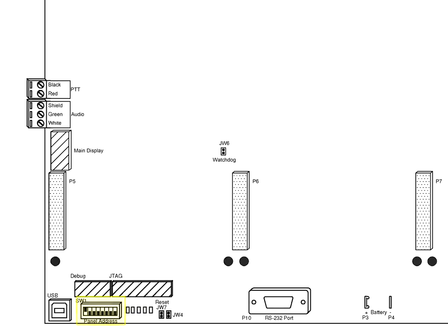Moving on, we can see a bank of dip switches, which is where you will set the address of the panel. The master panel will ship as address 1 and should stay that way. Booster panels will ship as address 2, so if you have more than one booster panel, make sure to change the address to any additional booster panels being installed on the particular site.